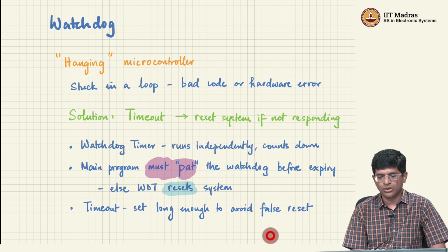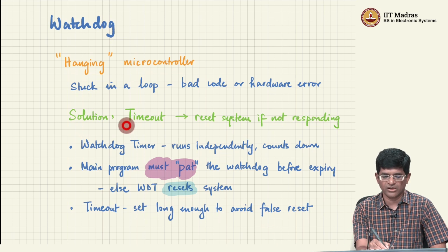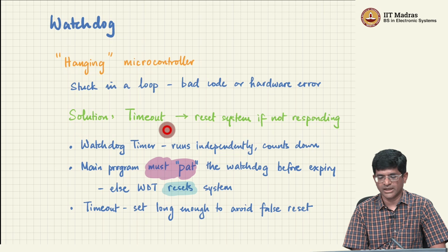Okay. Now, what do you do in such a scenario? Yes, you want to restart the system, but nobody can physically reach the system. So one possible solution is that you bring what's called a timeout, right? And you say that, look, if a certain amount of time has passed and the system is not responding, just force reset it. But then comes the question, who's going to handle the timeout? It can't be the CPU, because the CPU is the one that's actually hanging out there.